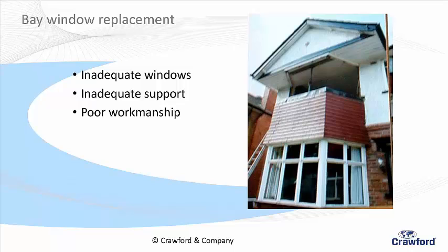In a normal window you've got a lintel; if you take the window out, fine, you take it out, go for a coffee, come back to the new window, it doesn't really matter. On a bay, you've got to be really careful because a bay by definition is a piece of construction outside the line of the normal construction of a wall. It's lightweight, it's to allow more light in, it's a lighter weight construction on a more shallow foundation.